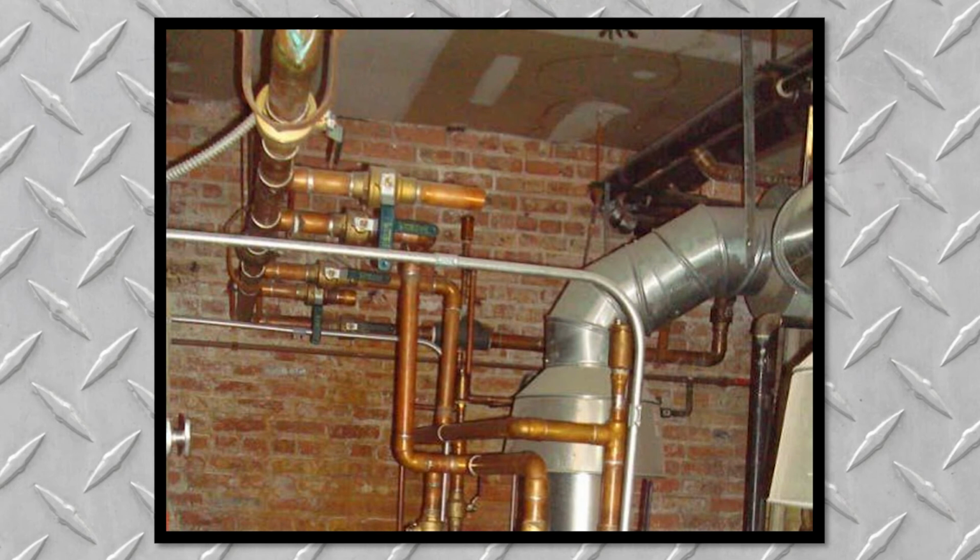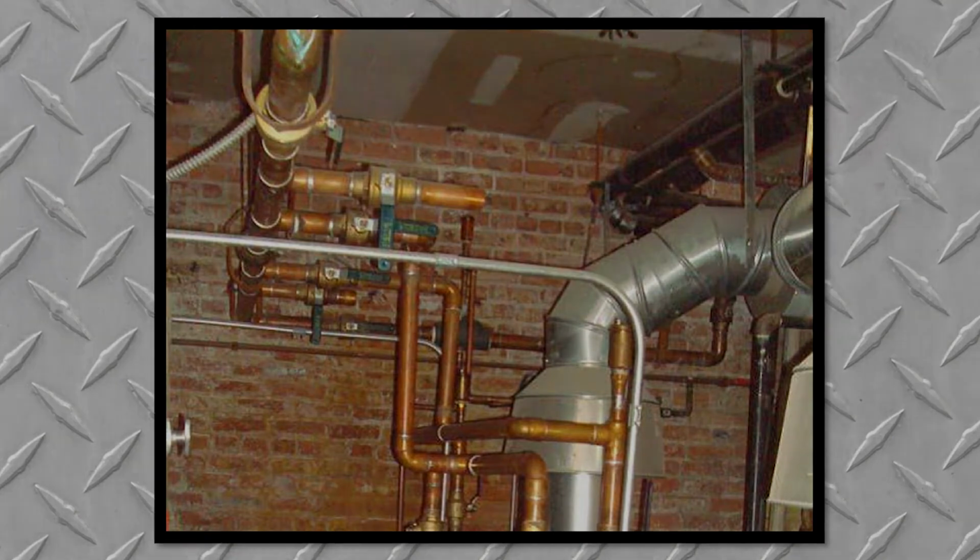So during an assessment, you can walk along the piping looking for leaks and feel if there is any water being held by the insulation. It'll be spongy. Another thing to remember is that the condensation problem is going to work against us in terms of vertical piping. In the picture, several joints are not insulated, and although there is minimal pipe uninsulated, the condensation will occur and will run down because of gravity into the insulation and compromise it. A place where we don't love gravity.